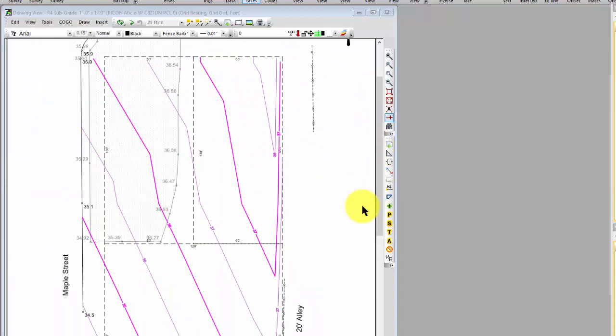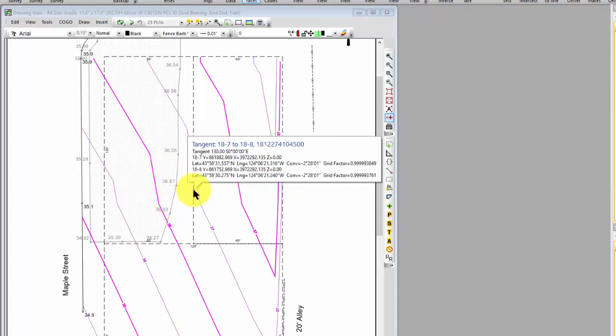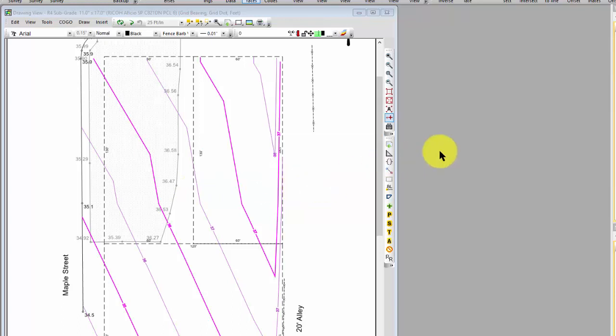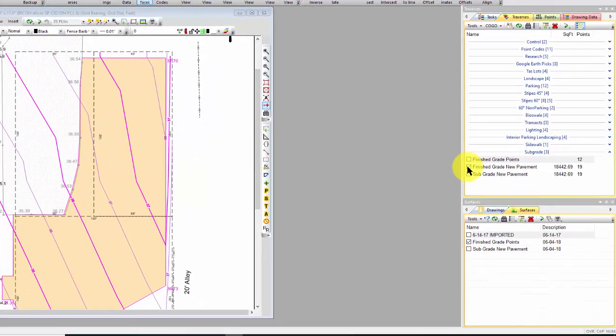Okay. My water is going to flow from the northeast to the southwest. I've got a 2% slope west, a 1.3% slope south, but I've got these existing grades I need to retain on this existing pavement. So that's the little kink that gets put in here. Okay, this is kind of one of the magic parts to this then that I think is kind of neat. I basically said, okay, I've got just a certain part of this project that I need to do subgrade work on. I'm going to retain this pavement here.